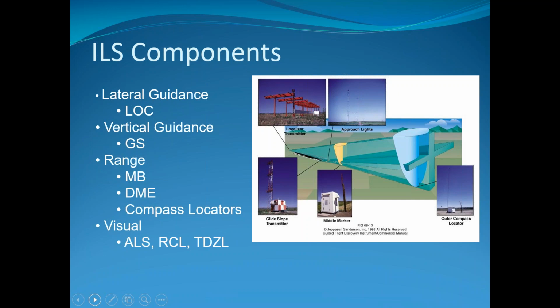But anyway, an ILS is one of the precision instrument approach systems. So you have precision and you have non-precision. Non-precision approaches give you horizontal only. Okay, so write this down. This is also something you need to know. You might be asked, what's the difference between non-precision and precision approaches? Non-precision is going to be horizontal guidance only, and precision is both horizontal and vertical guidance.